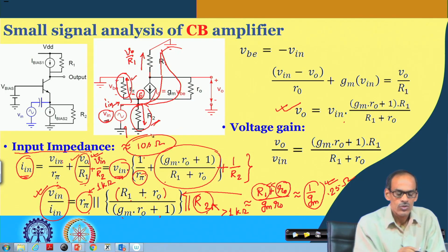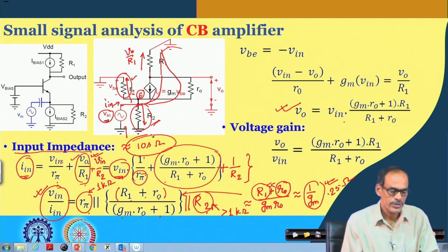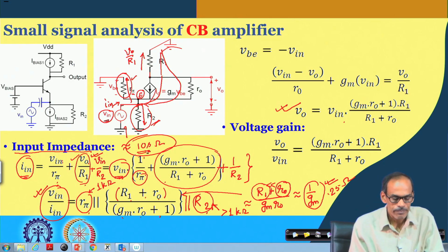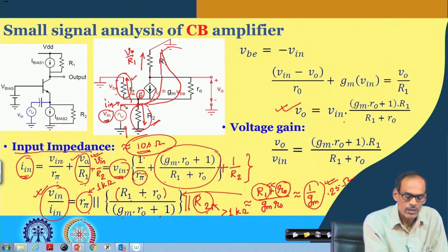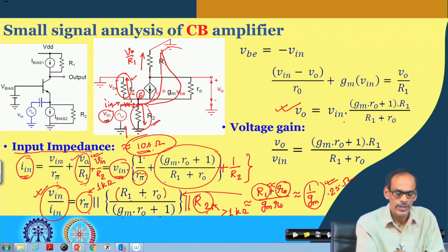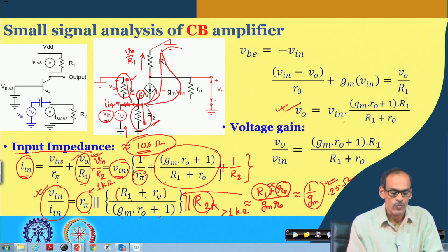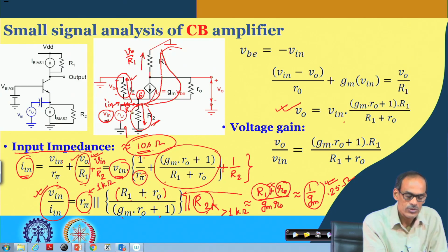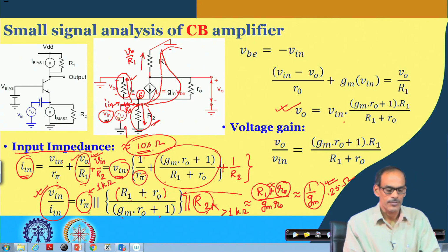Of course, it depends on the DC condition, but the important note is that the resistance is very small, and if I consider the source resistance, then this input resistance and source resistance will be making the voltage coming to the emitter of the transistor very weak. So, we will see what may be the consequence if I consider source resistance of this circuit.